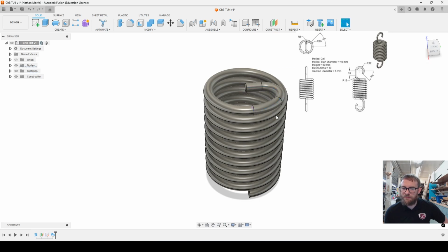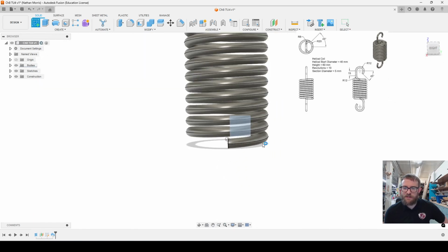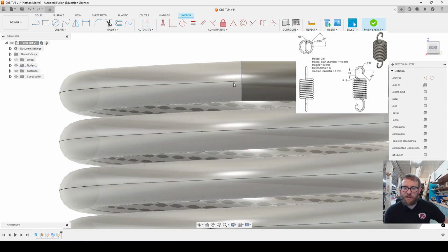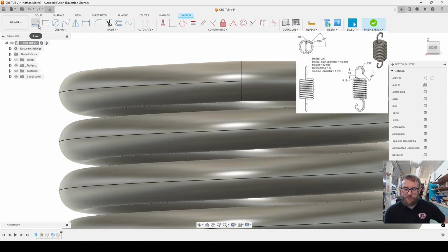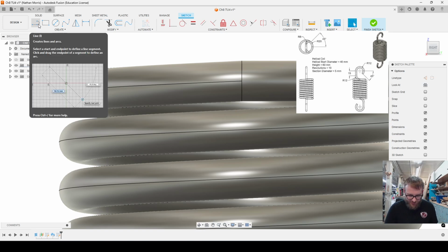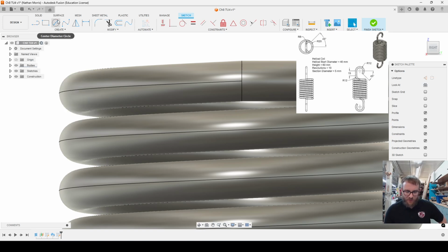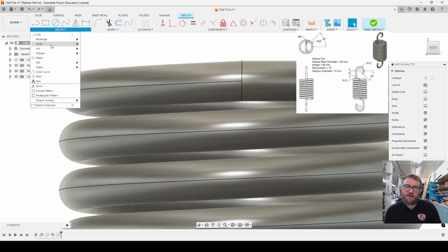So that's the part that brings it to the middle, and then we need to create the part that goes up. So we'll go to create sketch, we'll do it on the right plane this time, and we'll start right up here. It is kind of a funny way of looking at it, but it will work out for us. So we'll use the line tool. Oh, actually I can't use the line tool, I forgot. Because we don't have a line that we're starting with, we can't do the arc. We kind of need a line first.